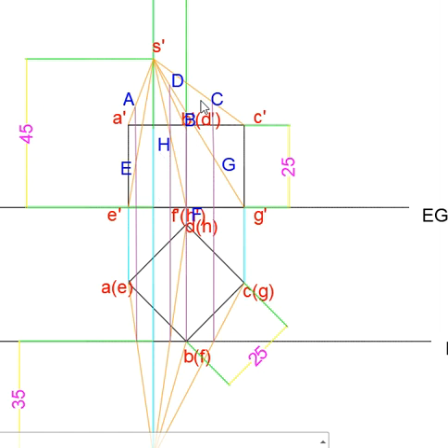Some lines are visible, some lines are not visible. You can draw the outer lines using continuous lines. So you can darken that portion, and inside points are there. Point B and point H is inside. So we can draw dotted lines connecting point H and all other points in the bottom surface.